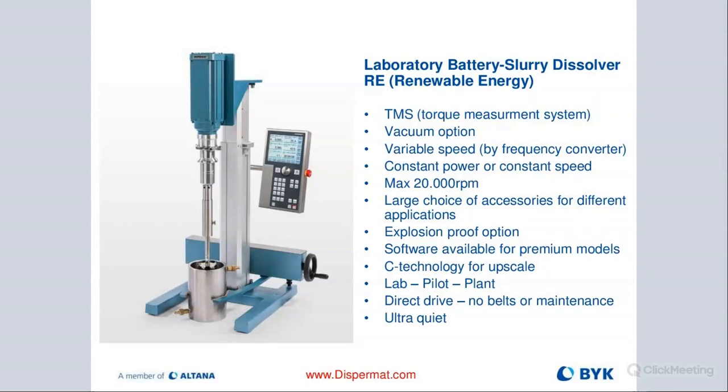You can program recipes, store them by batch name or product ID, and then port everything over to a computer and store it on there, or you just put it into an Excel file, and then you can create lab reports, share that with your team, and then also watch the entire dispersing or milling process in real time in a graphical interface where you would then be able to see trend lines for each of these variables that we discussed: your time, temperature, torque, tip speed, viscosity, in a graphical interface, where you see then change in the dispersion process very easily.